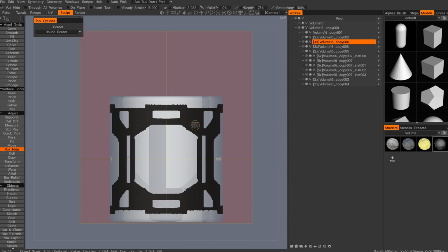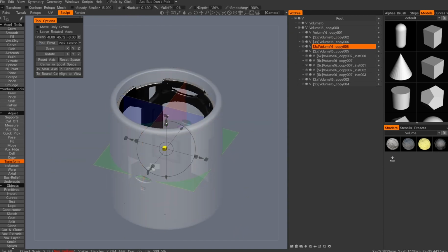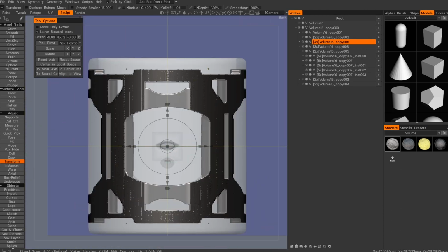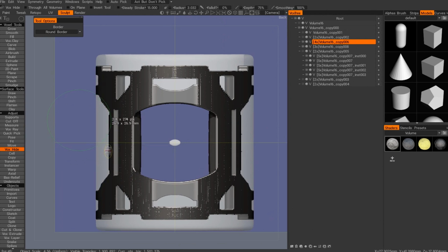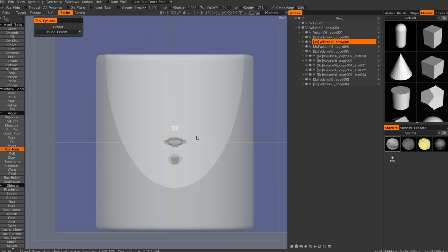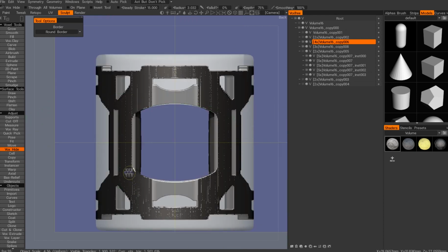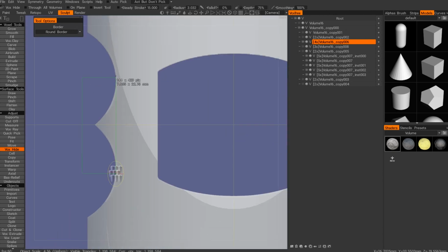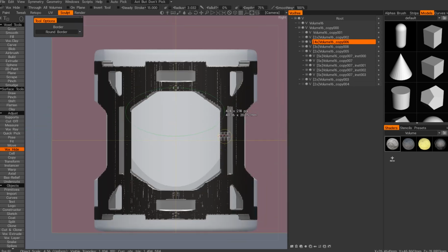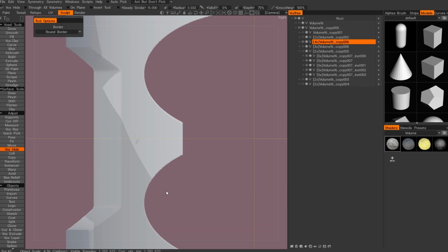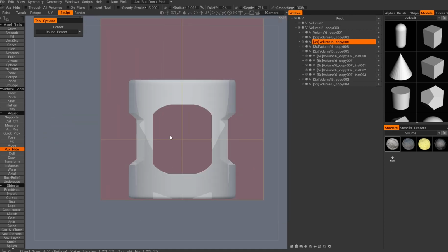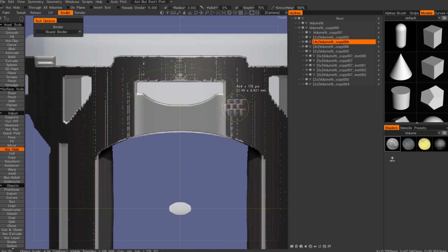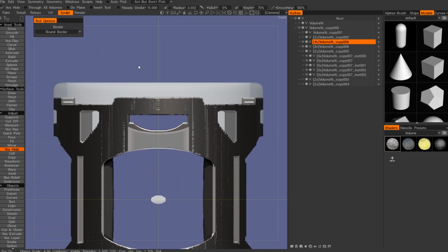So here I'm using voxels, because I wanted to recreate this holder, make it a bit tidier and with a high density of voxels. I used this particular volume material that allows you to see through, because if you go into ghosting mode in 3D Coat, ghosting doesn't allow you to modify the actual mesh. If I turn it into a volume, it's semi-transparent. It allows me to see what's going on behind this volume, and to do the same cuts as I did before. Right, just doing more holes, and framing the holes. So hiding and hiding constantly.